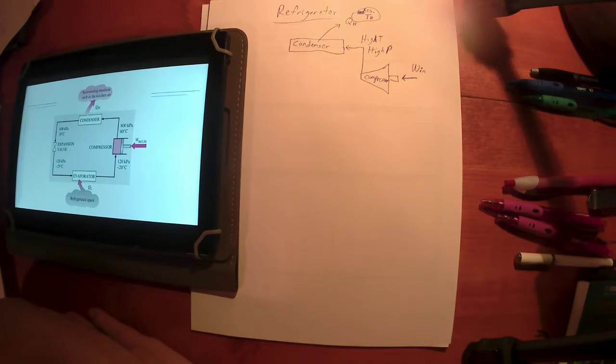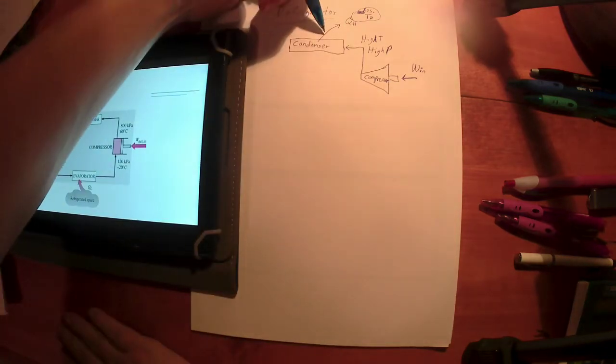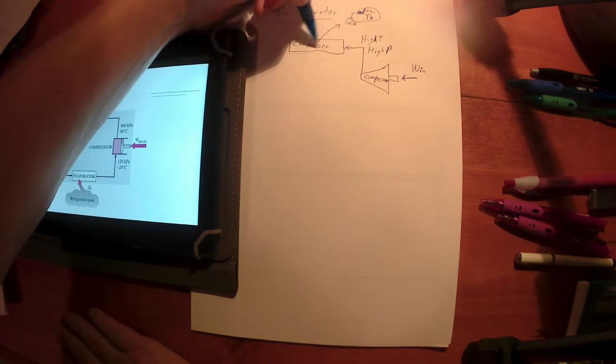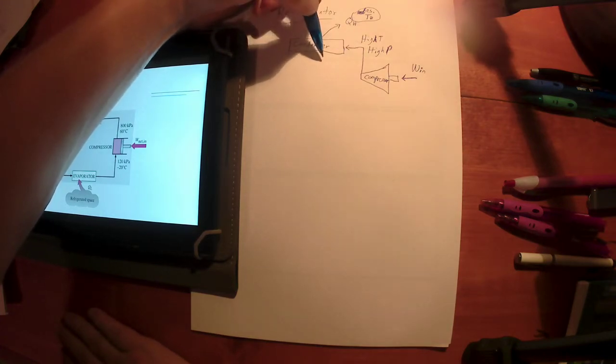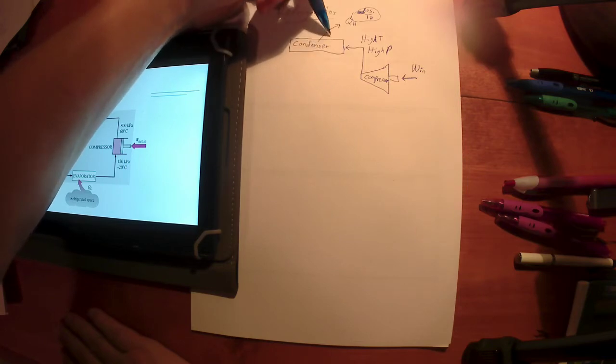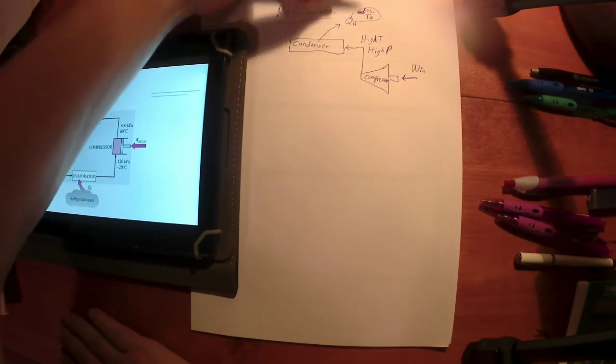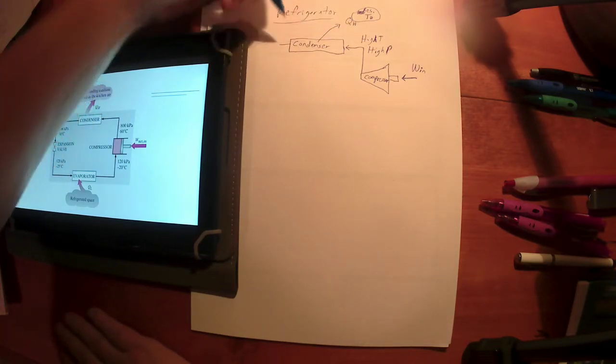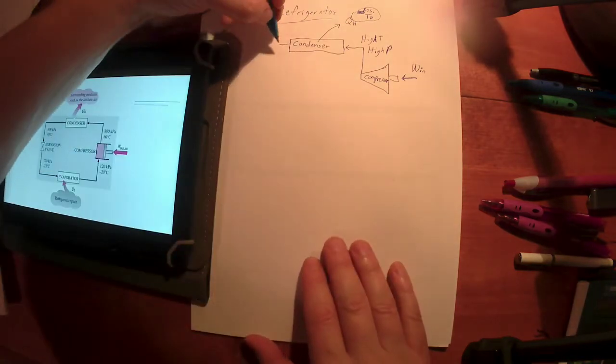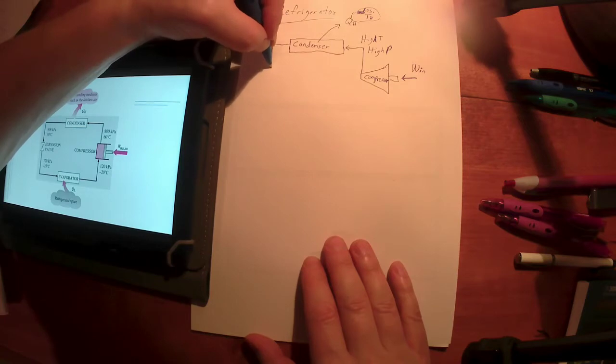Okay. If you walk by the outside of an air conditioning system, the little tower that sits outside with the fan in it, or if it's a window unit, the coils, the aluminum fins on the outside, you walk by one of those when it's running, and what do you feel? You feel this heat. That's the condenser coils. Refrigerant's flowing through there, it's going to push air through there, and that air is used to basically remove heat from this refrigerant into normally the outside air, or in the case of your refrigerator in your house, the air inside your kitchen. So it's removing heat to a higher temperature source.